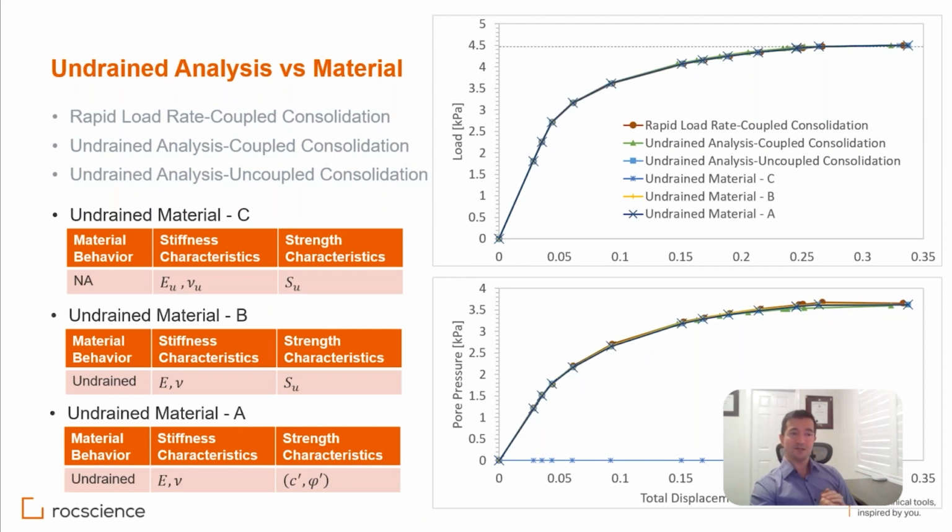Okay, and maybe, yeah. What I would like actually in this scenario in terms of analysis, this is my favorite. Historically, I have been working with the UP formulation. It's the whole major thing at the top, and the other ones are derivative of that. When you are doing that consolidation analysis, usually you have everything defined in terms of effective, and everything else, if it is undrained or whatever happens, is defined by the permeability or the time that you have for the analysis. It's going to be handled in those terms.